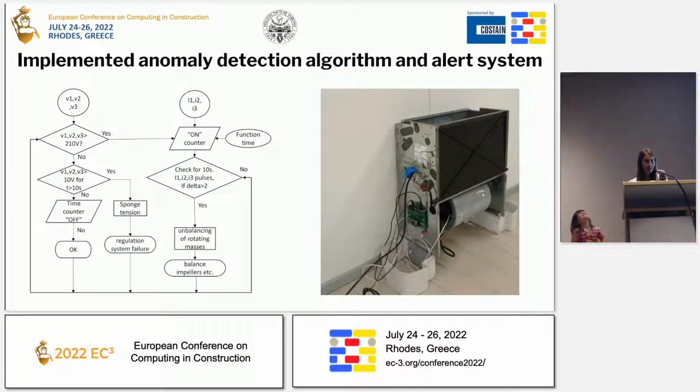According to this automated fault detection and diagnostic methodology, an alarming system is implemented to monitor the FCU motor impeller, monitoring the motor voltage between 0 and 200. For this reason, the motor voltage must be checked more often, and the sensor board must send average readings to the server every time the FCU is started or changes speed.